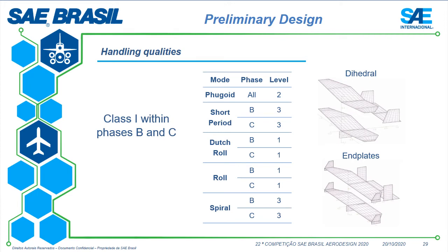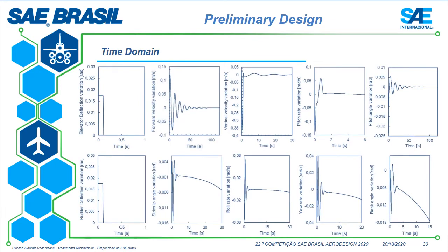As stated in the aerodynamics study, the geometry with end plates was selected because it makes a larger improvement in roll stability, is easier to manufacture than the dihedral angle, and improves the aerodynamic efficiency. The time domain response of the aircraft shows that the longitudinal response converges, and the lateral directional response diverges. Despite this, using theoretical results computed by the team, the experience in previous competitions, and the design decisions made for the present year model, it is prominent that the aircraft is reliable and maneuverable.